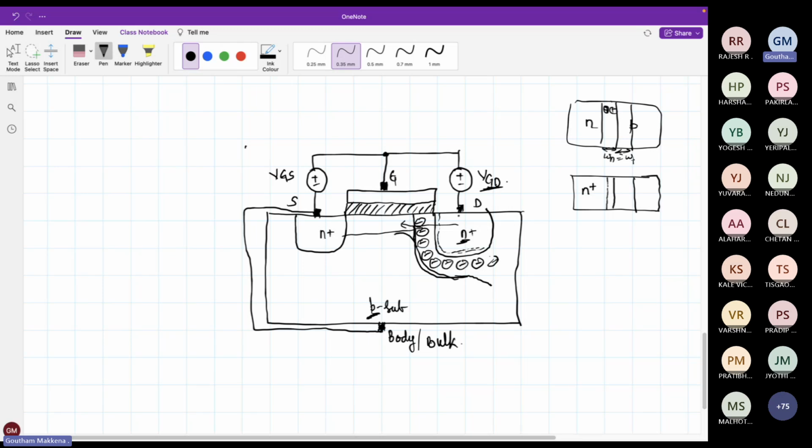Like you told, as I increase the electric field, the charges should increase. In the same order, this depletion region might be reducing those, and both effects are canceling out, and in effect, I have the same saturation current. So you get the picture of what I'm trying to give. It is not only one phenomenon going on; at the same time, so many things are happening. What I told is a very simplistic explanation of the saturation current being very low.